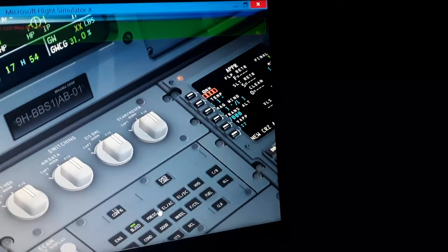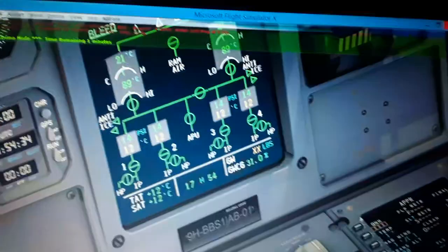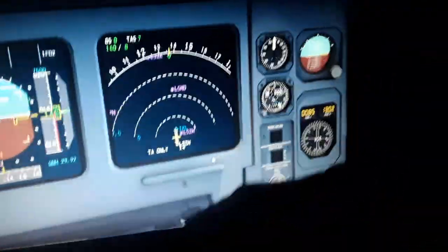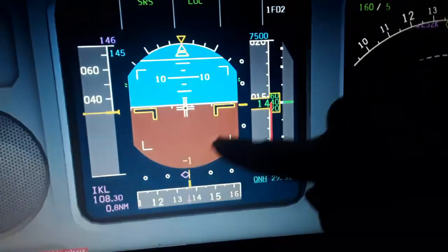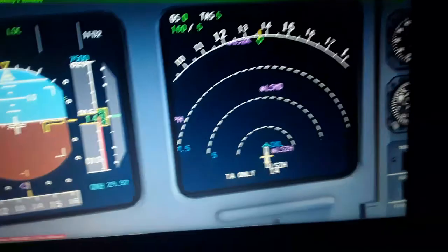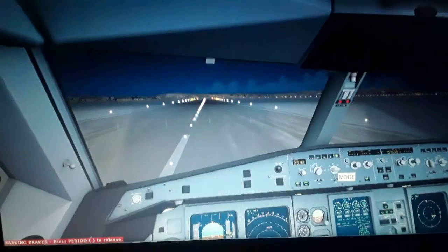The bleed system from the engines, no leakage. The hydraulic, no leakage. I'll show you now. So we have the flight controls all working. And here's the mode engaged. We have the LSZH. You can see the localizer perfectly aligned. The altitude of the airport 1,400 feet, and we are just engaged into a mode for takeoff go around, just in case of a missed approach or another problem.